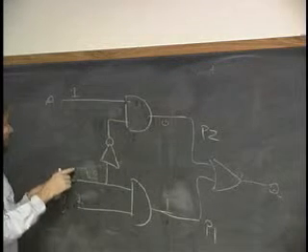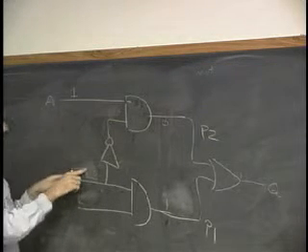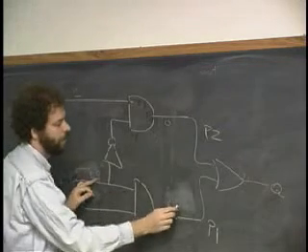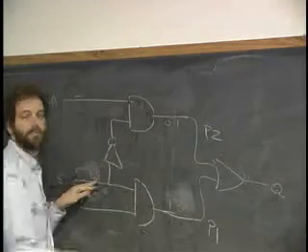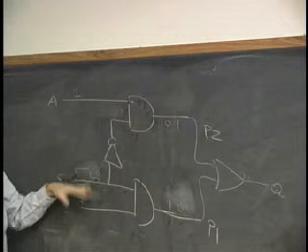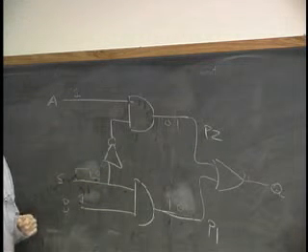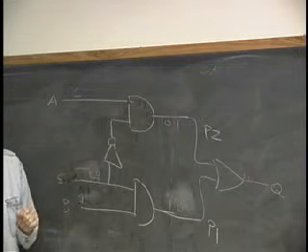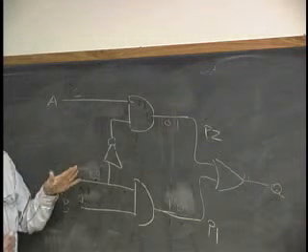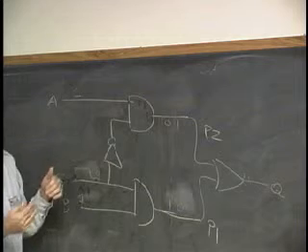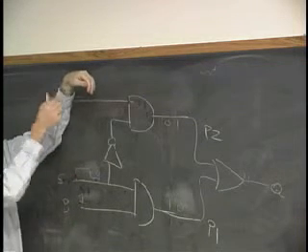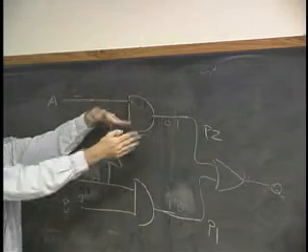And then I'm going to switch S. I'm not going to change these guys. I'm going to drop this one down, which will turn this one off and turn this one on. Right? Basically I'll be saying, okay, stop letting B through and start letting A through. There are 2 gates, and I'm questioning which one is going to be open. Think of the selector as being made up of a whole bunch of gates, each one gating each of the inputs to say which one gets to race to the output.